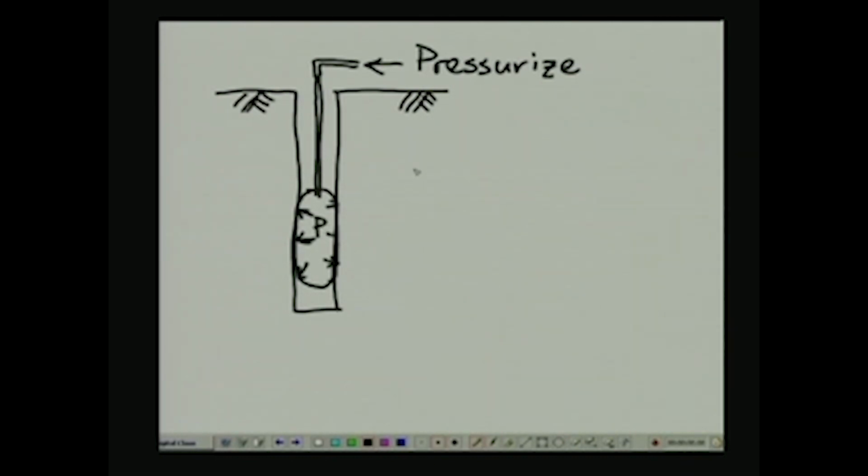So we keep track of both pressure and the diameter of the borehole as a function of the pressure. Now interpreting these data, we can find out the in situ state of stress as well as other deformation characteristics of the rock around the borehole.